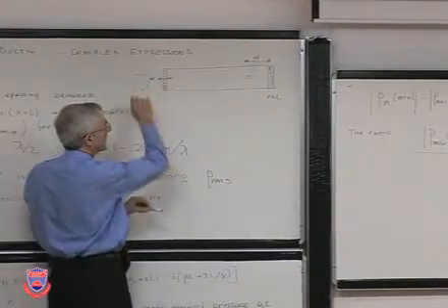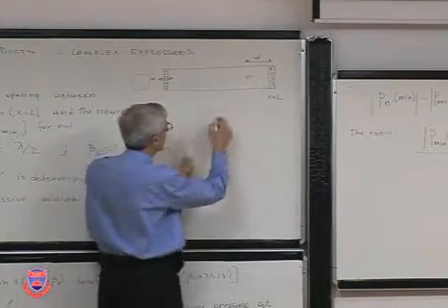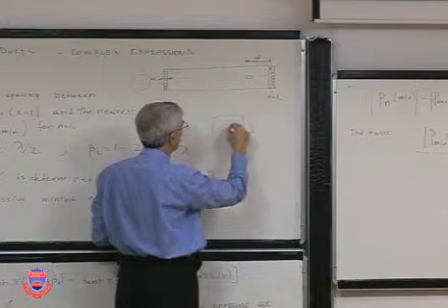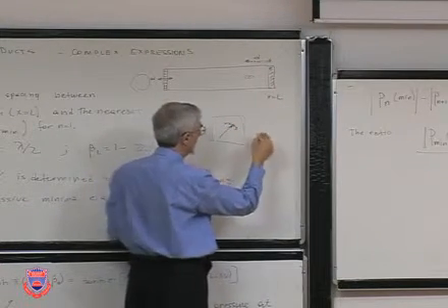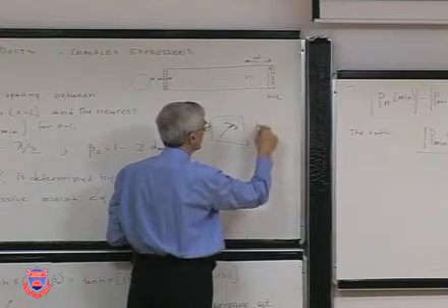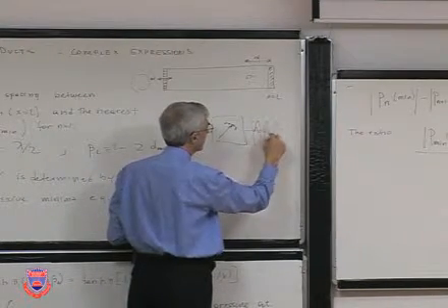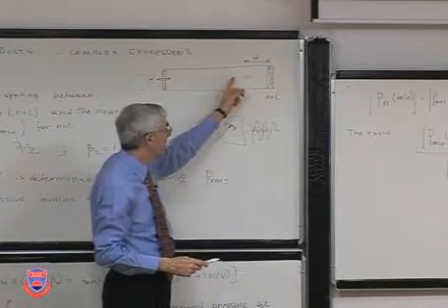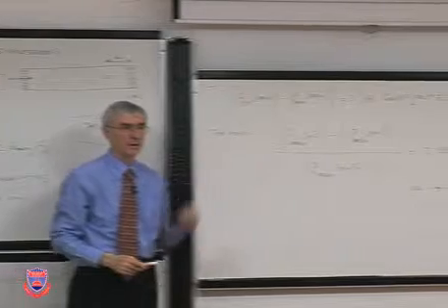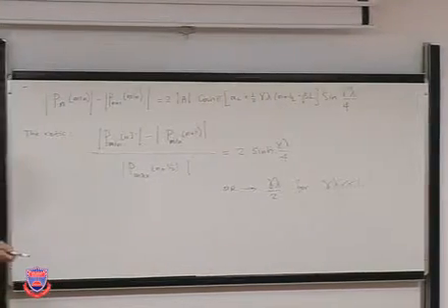You start pulling it out, and either you look at the sound level meter, or you look at the oscilloscope to see what amplitude change there is, and establish two minima, and the maximum between them. And that gives you that particular result.